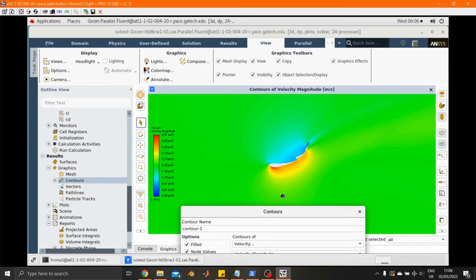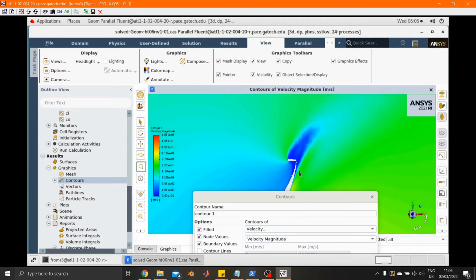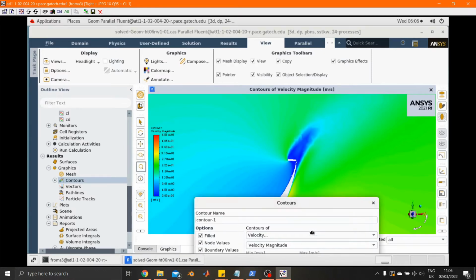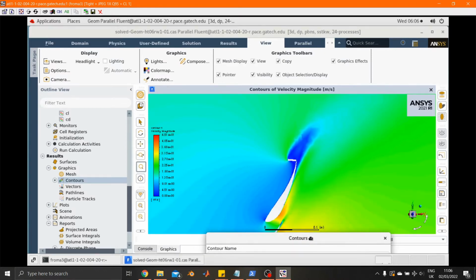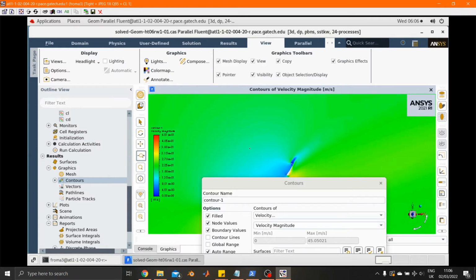Velocity is also very good for finding separation at the trailing edge of elements. We have a gurney flap there, which you can see if I go ahead and zoom into that gurney flap. You can see that flow is being separated because of that gurney flap, but that's expected. That's not necessarily a bad thing with a gurney flap. That is always expected. But yeah, so that's another thing you can check. Let's just zoom out again. There we go. And drag it back into the middle.